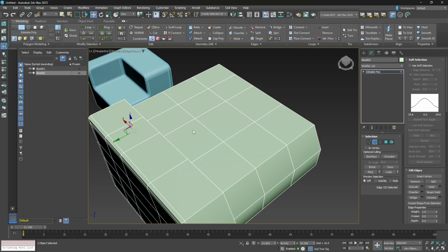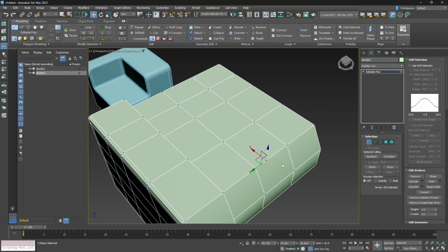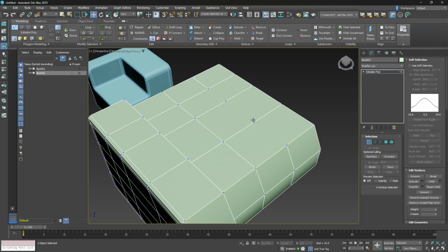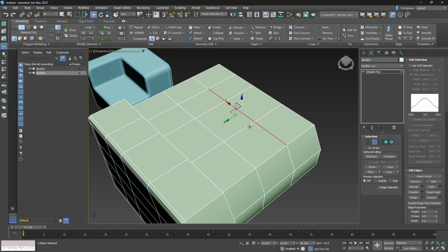Whatever the case, you see connect is over here. Okay. So no, you can connect with edges. I thought you did it with faces too, but maybe you don't. I don't know. Maybe I'm wrong. When you want to dissolve something, it's control backspace. You don't use delete. So if you wanted this whole thing gone and you backspace, it's going to leave vertices behind. So you want to go ahead and control backspace.